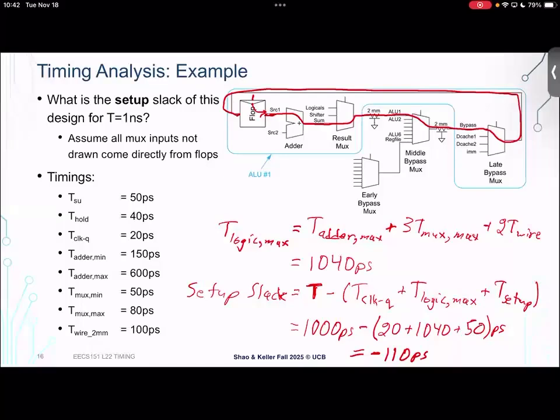I'll give one example, a sort of generic example. Think about when we were analyzing the delay of CMOS gates, and we said anytime we have transistors in parallel, we need to size them for the worst case when only one of those transistors is on and driving. That's the slow case, right? But we also have a fast case where both of those parallel transistors are on and driving. And so depending on exactly how your inputs are toggling, you might have a slow delay through that gate, or you might have a faster delay.